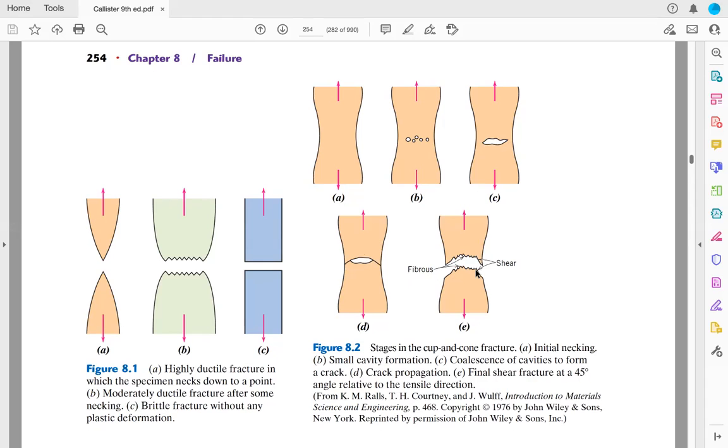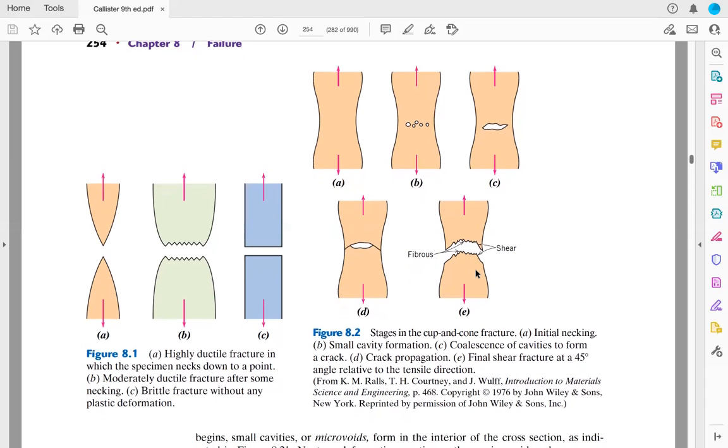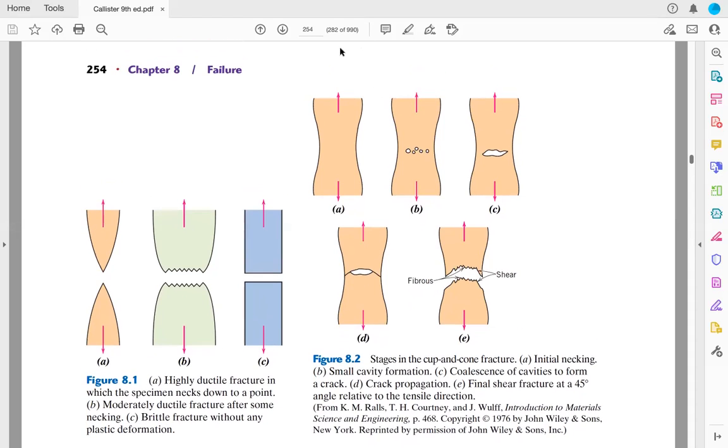Okay, ductile fracture is actually something we are okay with, because with ductile fracture we can know that the metal will start the fracture process, since before the fracture happens there would be some deformation here. So if you investigate your chemical equipment at the plant and you notice some plastic deformation, you may become curious: okay, I think I have to check this equipment.